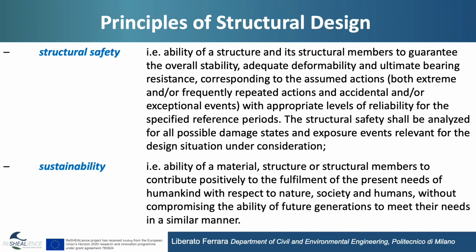Then we have to consider structural safety. Structural safety means the ability of a structure, of a structural element, of a structural member, to guarantee adequate stability, adequate deformability, adequate ultimate load-bearing resistance, corresponding to the actions which are assumed in the design, both under persistent combination and under accidental or exceptional situations. And these performances have to be guaranteed with an appropriate level of reliability, once again for a specified reference period, and for all possible damage states and exposure events.